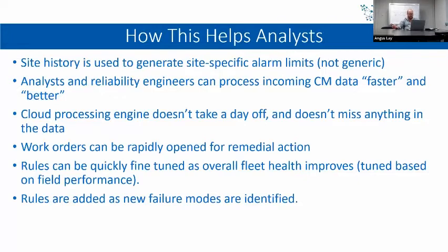Essentially, what the system does is break that traditional condition monitoring loop where an oil sample comes in with dirt ingress, we go out, we change the oil. The next sample comes in, potentially someone else on swing, they go out, they change the oil again. Next sample comes in, we've still got dirt. You're not actually getting to the root cause of the problem.